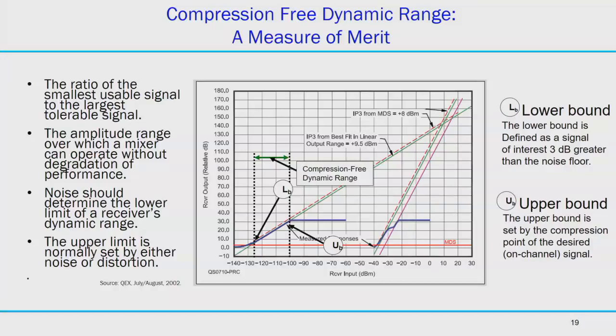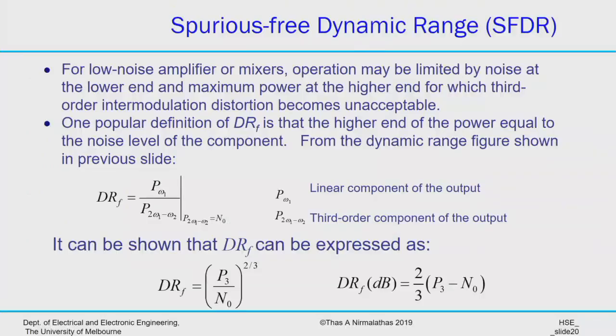But now, if you wanted to work out the power range of the input when it is distortion free, this is the dynamic range of the power levels from here, where the signal is starting to be above noise and linear, up to the point where the intermodulation starts to pick up. This is the range that is important. And you can see this range has something to do with the intercept points. If you use two triangles, you will see there is a direct relationship between the height of that intercept point and that range. That's why it's important to find that intercept point.